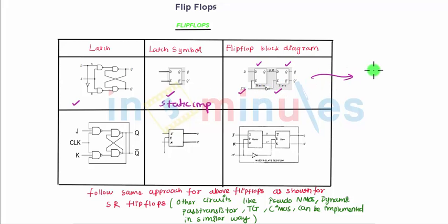This static implementation needs to be replicated twice, with the first getting a clock at its enable and the second one getting a clock bar at its enable at the transistor level. You can easily do this, the inputs need to change and you need to connect cascaded latches and it becomes a D flip-flop. Similarly, we can do the same for JK latch.